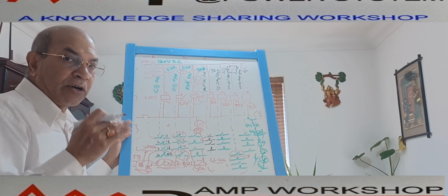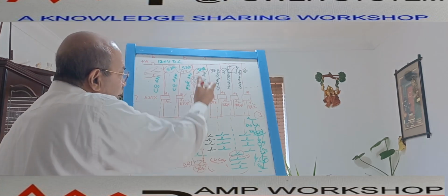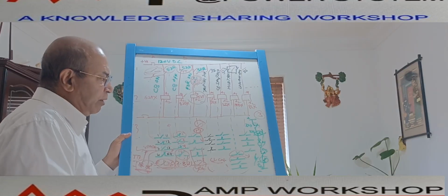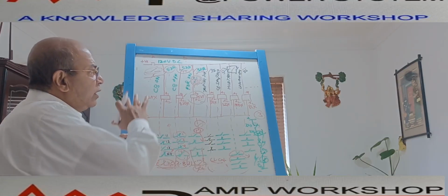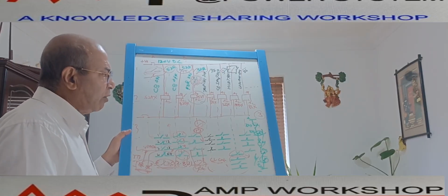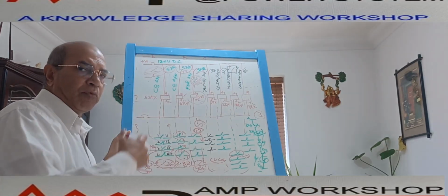Feeder on condition is not readily available with the circuit breaker. We have to develop that scheme, develop that auxiliary contact using this circuit. Similarly, these are the various auxiliary relays I have used and how the contact is shown. So this is what we call an auxiliary relay circuit or auxiliary relay scheme. This way we can have multiple relays for other functions.